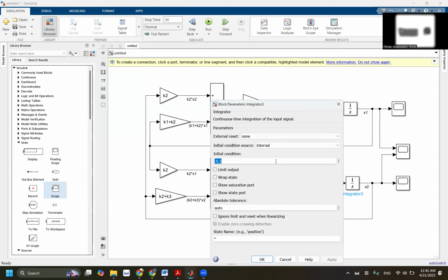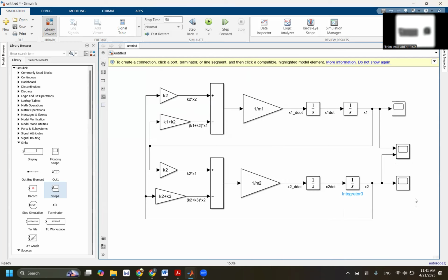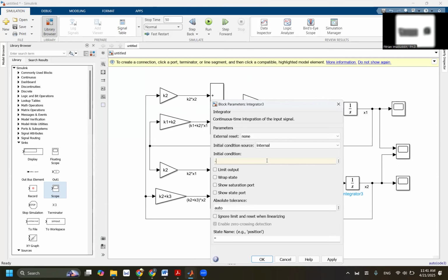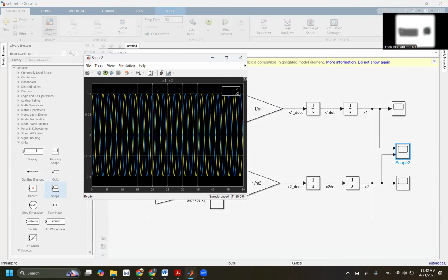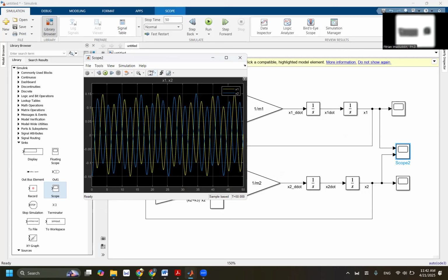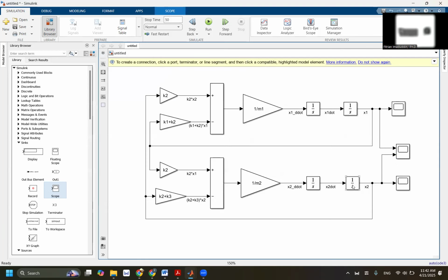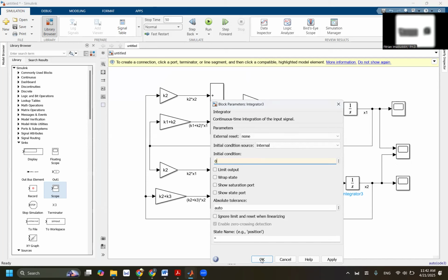So if it's not satisfied, say turning it back to 0, or not just 0, I'm just adjusting that a little bit, 0.15. Slightly adjusted. What will happen is we start to see some differences because now it's not 100% in the second mode. Some of the first mode is actually coming to interfere. It's a combination of both. So the more combination you have from both, the more chaotic the motion seems.